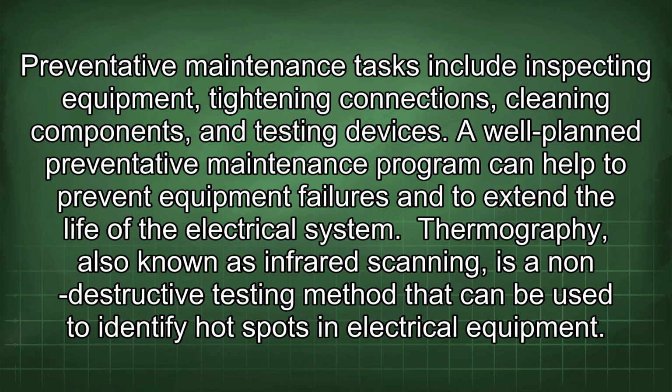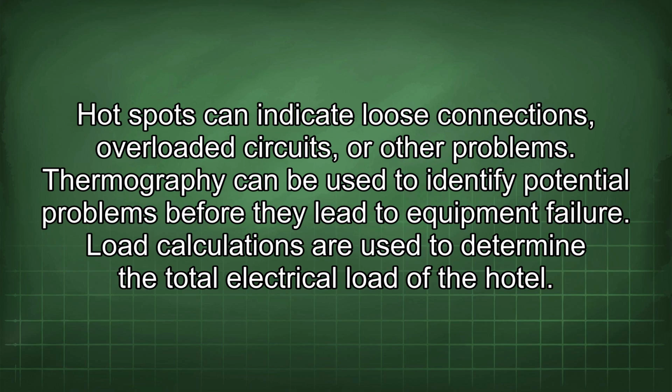Thermography, also known as infrared scanning, is a non-destructive testing method that can be used to identify hotspots in electrical equipment. Hotspots can indicate loose connections, overloaded circuits, or other problems. Thermography can be used to identify potential problems before they lead to equipment failure.